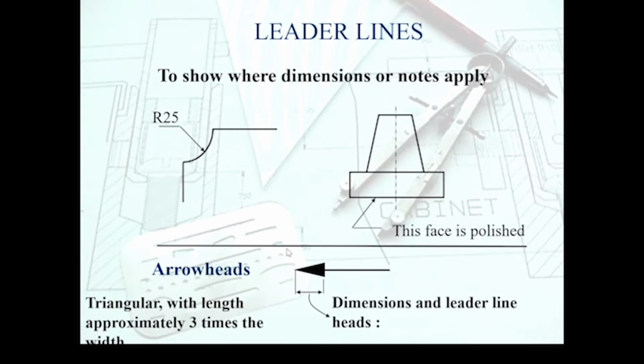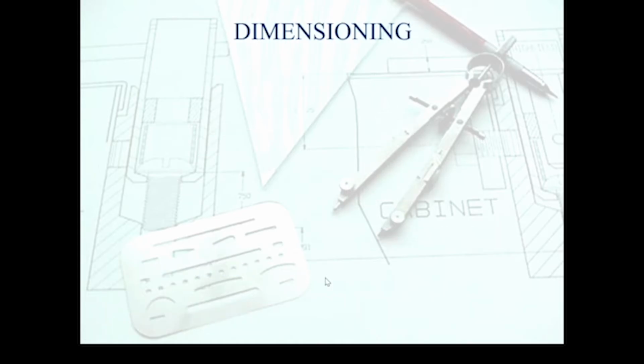Now, British Standards is very particular about the arrowheads and the arrow kinds we use. They need to be long and slender like these, and they need to be filled in. SolidWorks by default will not produce these arrowheads, so you need to go in and change that. I'm going to make another video showing how you can do that in the end. Arrowheads need to be about 3 to 5 millimeters long, and it's very specific in terms of the dimensions of the arrowheads as well, or the aspect ratio.